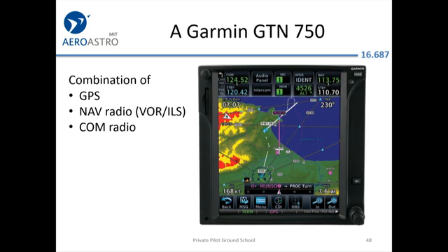All right, what does it look like in practice? This is the pilot's view. This is a modern Garmin 750. It's a single box that actually has 3 sub-boxes. And the sub-boxes are the GPS, a nav radio, which lets you tune up VORs and the instrument landing system for approaching the runway. Tina may talk about that a little bit tomorrow in a little IFR intro. And also a comm radio.